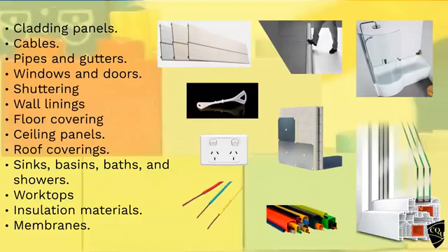And that's all there to give it strength, and the air voids also manage to entrap some air as a thermal insulation to stop a cold bridge. Imagine if this is the outside, and this is minus 20 degrees, and in here it's 24 degrees plus. If that was solid, then this minus would be minus on the inside, and you get condensation. So all this is insulation to stop transfer of heat through the tube, and that's a triple glazed window as well. These would be filled with an inert gas, not air, by the way.